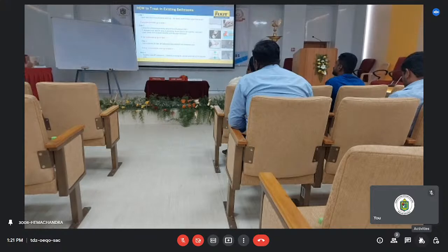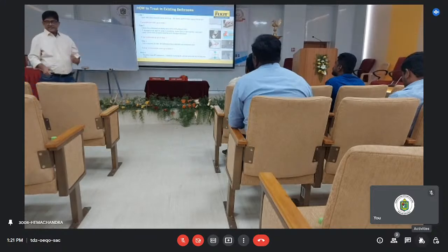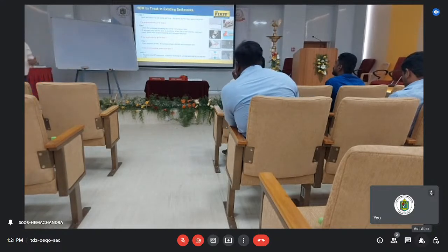Then, what is the step? We have mentioned the steps here, how we should go. Open and clean the joints and the trap and fill them with the epoxy tile grout that we have already told about as the first step. If that goes well, fantastic. The areas will be dry and then you can do the inside part of it. If that does not work, then where is the next source?